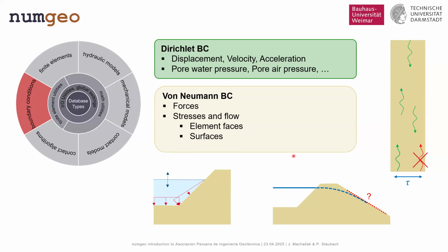For example, just to give you a few quick examples, it's not a complete list, but you can use compliant base boundary conditions. That's a boundary condition that you can use to apply an earthquake loading. And if then the earthquake or the waves travel to the top, let's say we have a one-dimensional soil layer, what would happen is that the signal will be reflected at the top, travel back to the base.